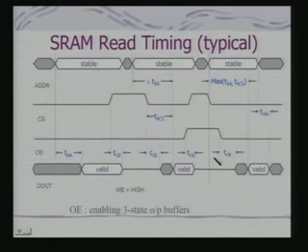Now, let us look at this timing in more detail. So, this is a typical scenario where I have also assumed that at the output stage there is a 3-state buffer. So, one of the states is a tri-state high impedance state, and I have got the output enable signal which enables the output buffer. So, here we have got more timing parameters which I have shown in this context.